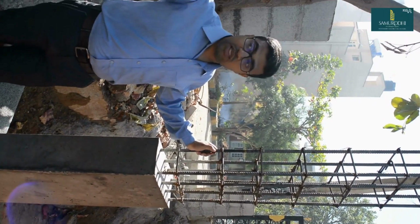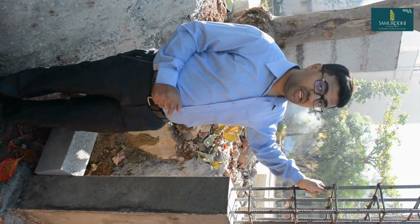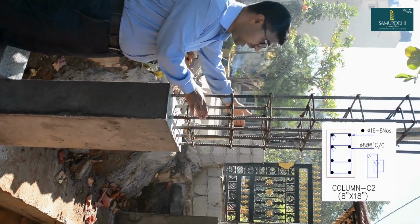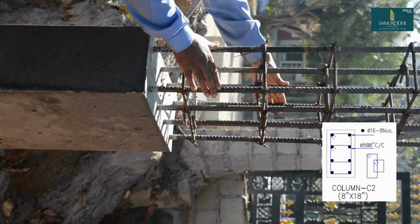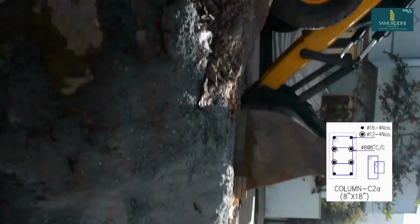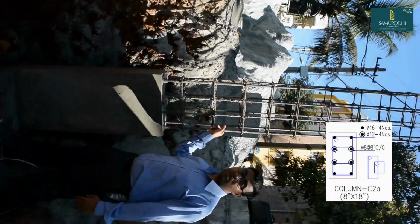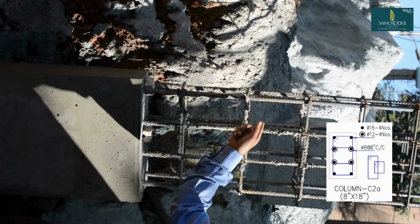And now what you can see here is that the column is not 6 inches, it's 8 inches, and all the rebars used are 16 mm, 8 numbers. So here one thing is the size of the column is changed from 6 inch to 8 inch, plus the rebars that we have used are a total of 8 numbers of 16 mm dia. So that's how it changes, friends.